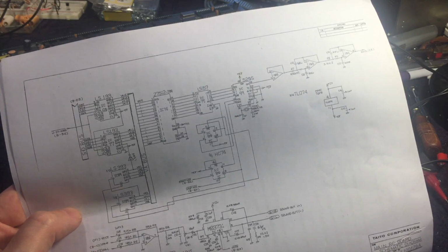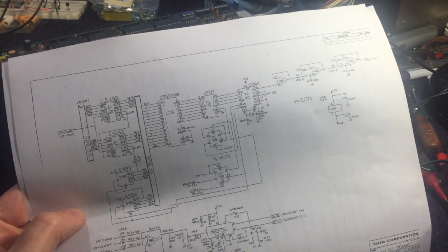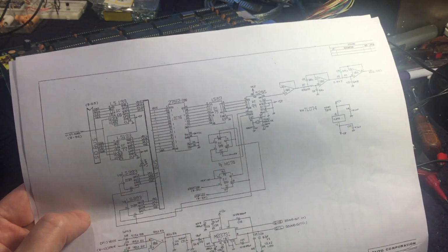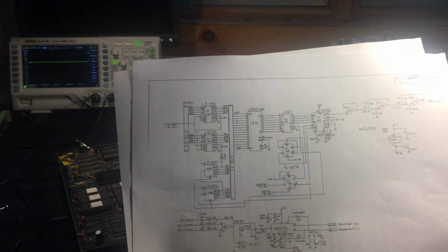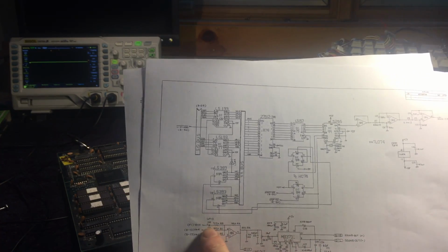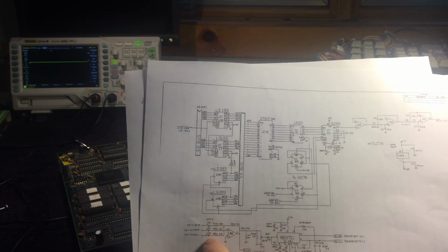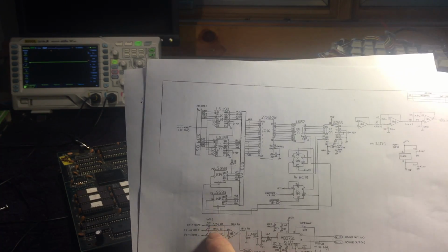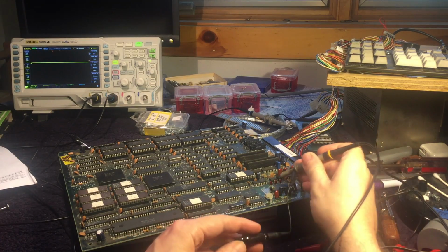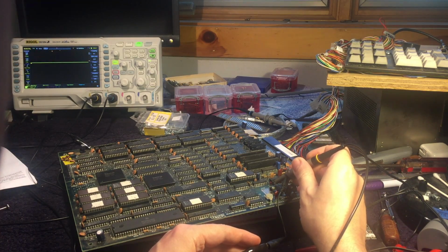So probably the easiest way to do that would be to just plug in, tap into this with the scope and see if there's anything showing up on it. Okay, got the scope turned on, and what I'm going to do is measure what's going on at these capacitors here, C18, 19, and 20. See if there's any sound coming out of those. And let's see if we get anything on these.